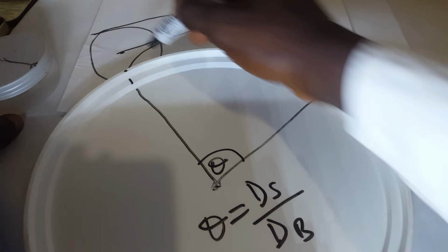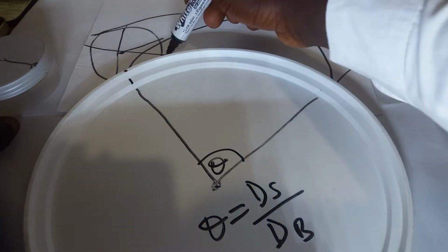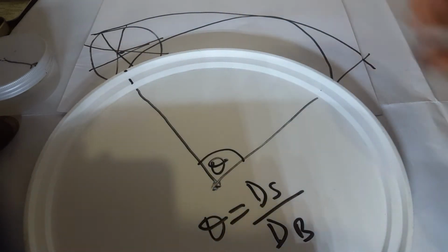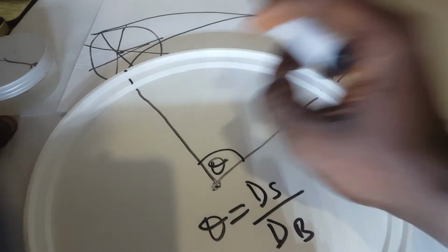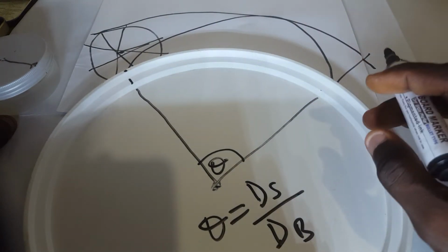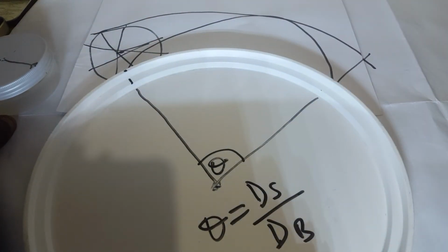So what we do is that we have to divide this circle here into 12 equal parts. I'm not doing it well, but we divide into 12 equal parts. We'll do that with our instruments right now. So when we divide into 12 equal parts, using the value of theta, we draw the epicycloid.